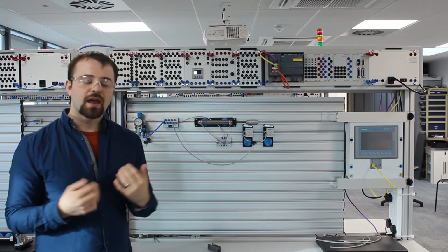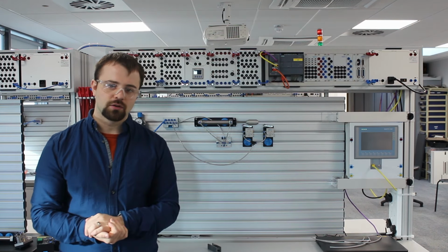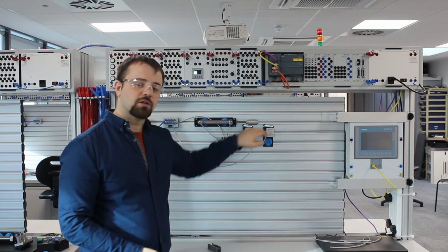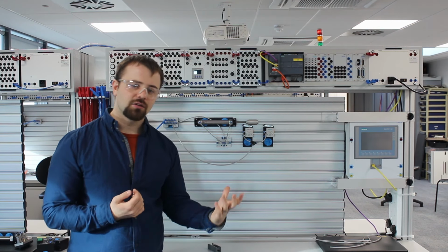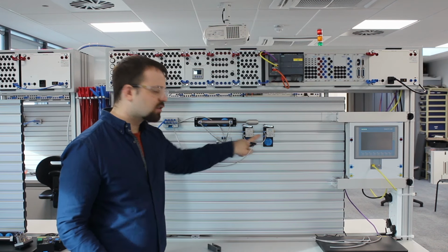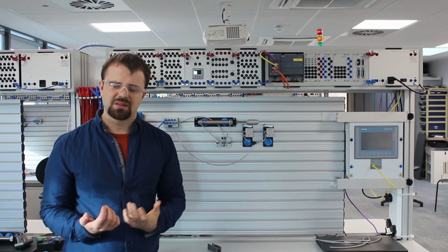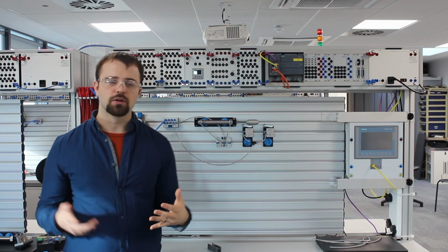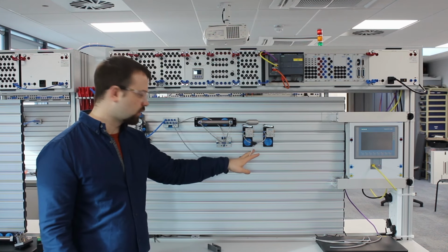Now you can do this anywhere where inputs are going into your system. So this is a 1 and a 1. Remember, it's just air going into the valves, so it's okay, we can split it like this. We couldn't connect the two outputs of the valve because that wouldn't make sense. You'd be putting outputs into outputs, but we can do it for our inputs in this case.